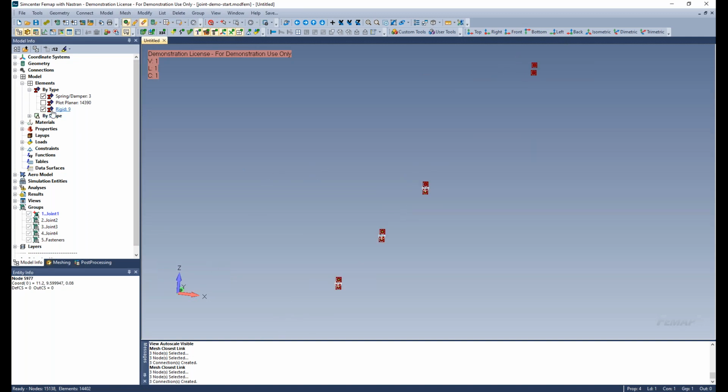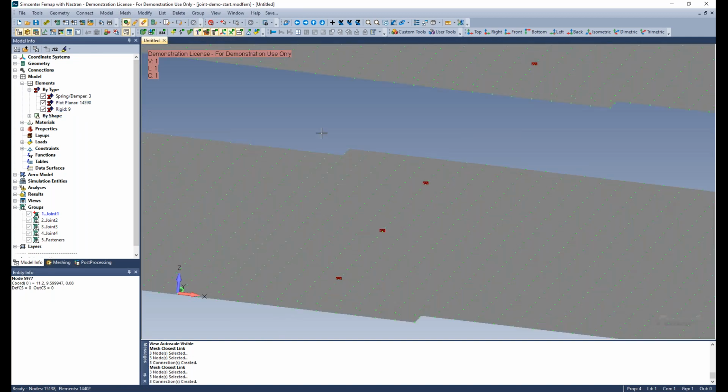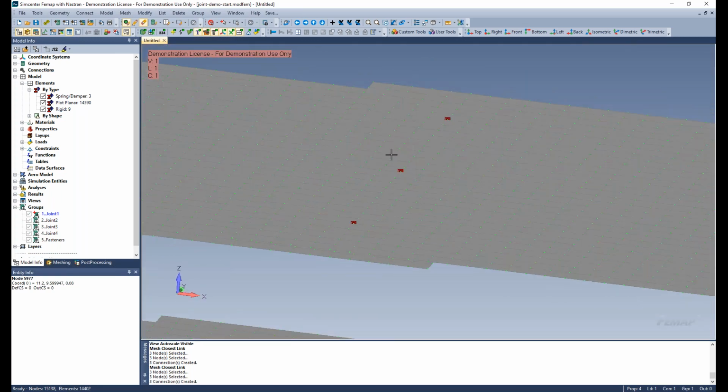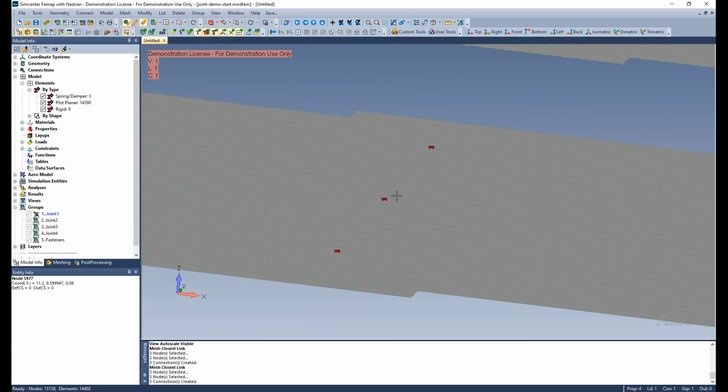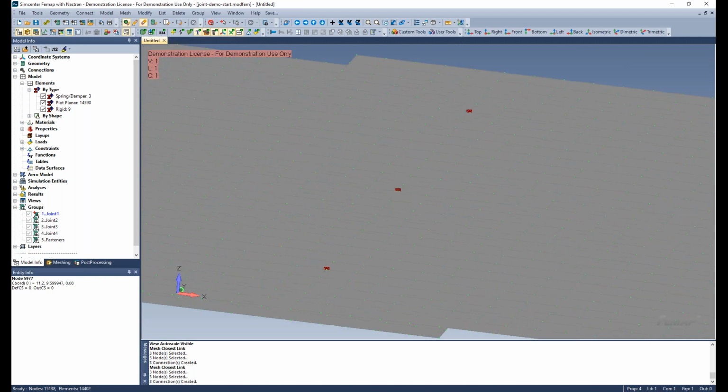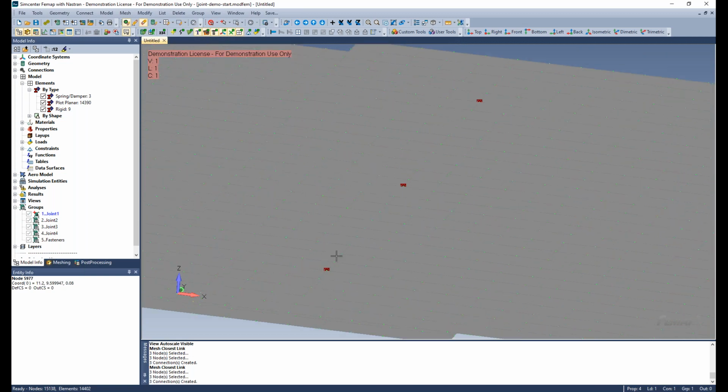So the next thing we're going to do is fastener elements, the CFAST. The CFAST, as I said earlier, is based on the location, and then you're connecting actual elements together. So it's a little bit of a strange beast. In reality, I have mesh points here because I wanted to keep track of where my fasteners are in space.